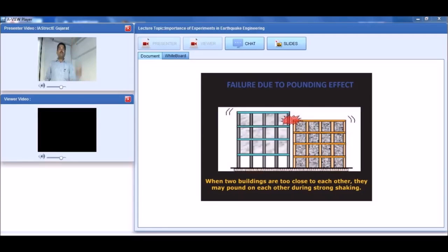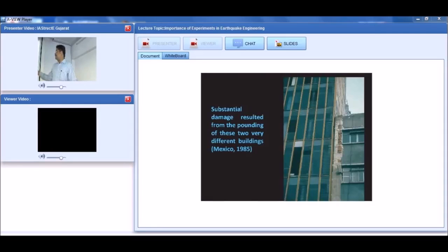Now we have designed this column for vertical load, meaning gravity loads. We have designed this column for the lateral load, even for the earthquake also, but we have not designed for this impact on the slab. And when the impact comes, we know the value is almost double as compared to the static load. Right? So we have not designed this column for the impact, and this column may fail. We'll see this next. You can see due to the pounding, the damage has been observed.